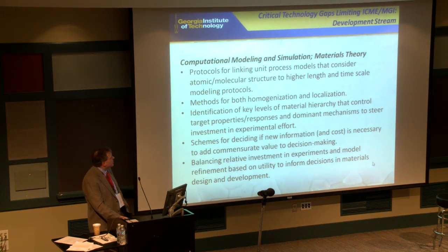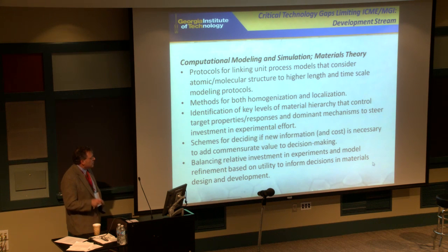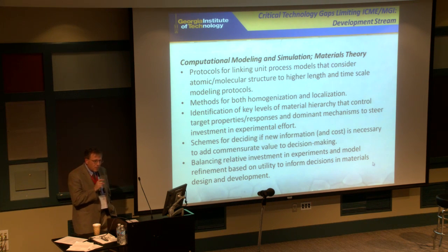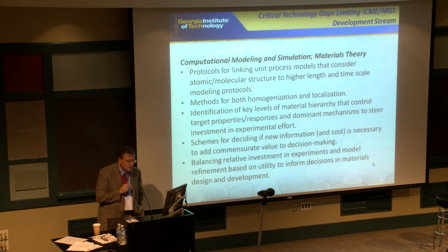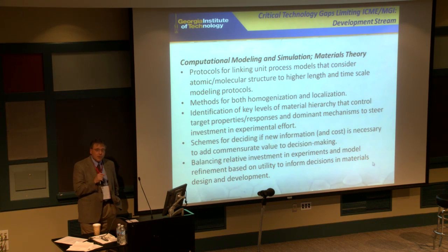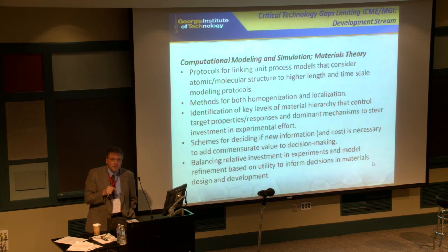Now, in terms of computational modeling and simulation, I'll let you read this, but the important point I want to make is that we talk a lot in materials modeling about homogenization, that is getting effective properties of microstructures using computational homogenization or some sort of bounding homogenization approaches. But we're really interested in localization most often because we're drawn towards life-limiting failure modes in service for aerospace components. These would include fracture, fatigue, dwell fatigue, corrosion fatigue, oxidation, etc.